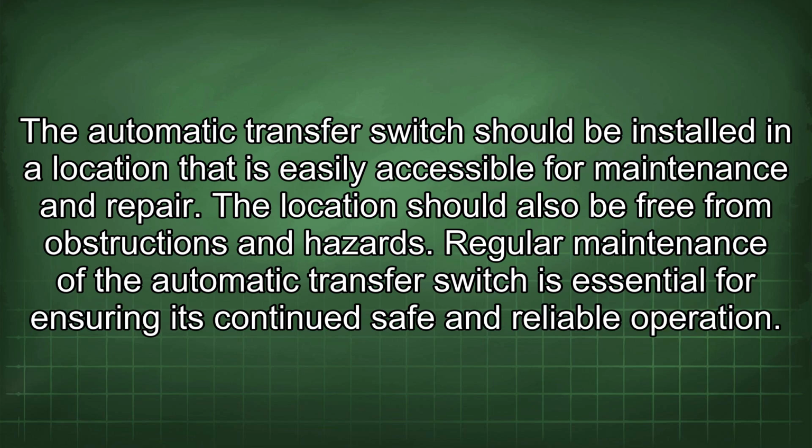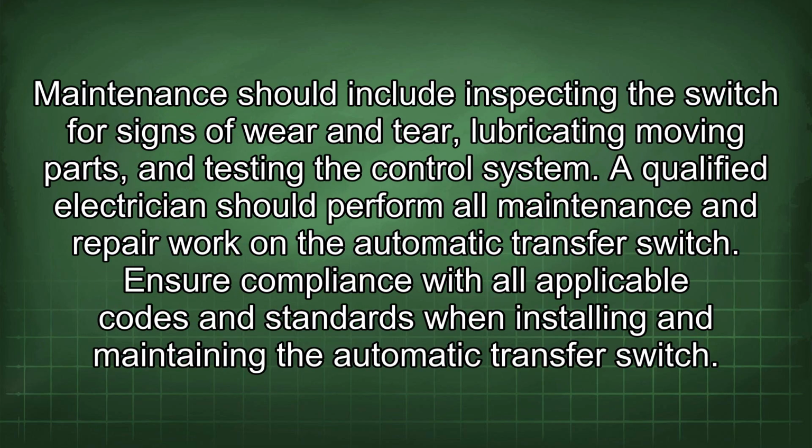Regular maintenance of the automatic transfer switch is essential for ensuring its continued safe and reliable operation. Maintenance should include inspecting the switch for signs of wear and tear, lubricating moving parts, and testing the control system. A qualified electrician should perform all maintenance and repair work on the automatic transfer switch.